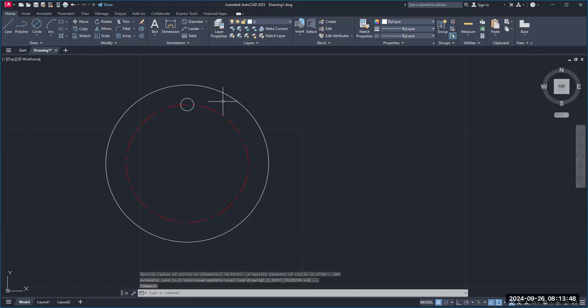What you just did is you drilled, you took a tap drill. In this case, the tap drill is a number 7. You don't know this yet, but you will soon when you get in the shop. A number 7 tap drill has a diameter of 0.201.